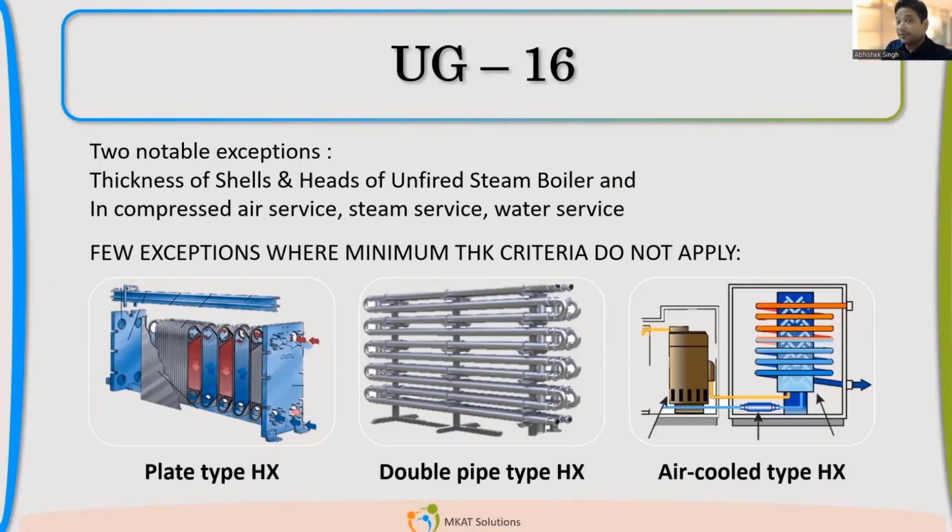If my thickness is very high, that heat transfer will not happen, so this type of product itself will lose its credibility. The purpose of making that heat exchanger is compactness and efficiency. So that is the reason the restriction is not there for plate type heat exchangers. You can use whatever thickness you are getting.